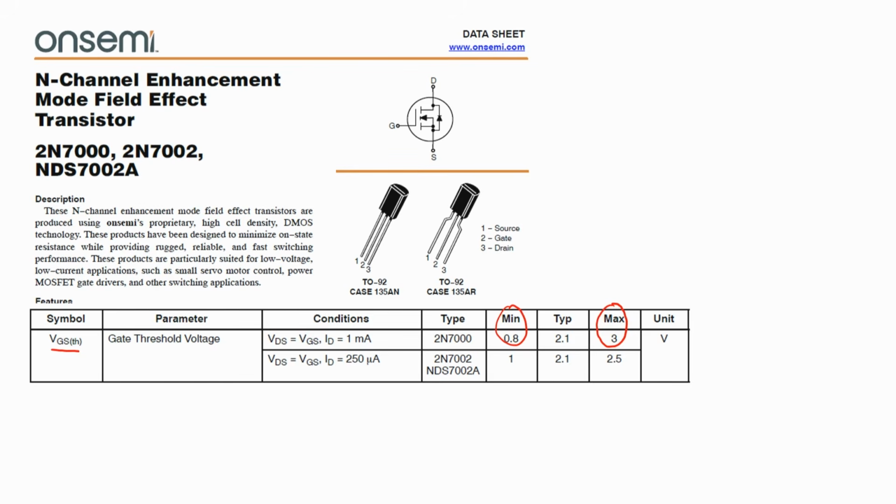With a bipolar transistor, you know that around 0.7 volts, that transistor is going to turn on. With a MOSFET, even if you choose the same MOSFET, well, it might turn on at 0.8 volts, it might turn on at 2.1 volts, it might turn on at 3 volts. We don't know. It might be random. So whatever circuit we design, we're going to have to accommodate different threshold voltages. If the threshold voltage changes, it effectively means that this entire curve shifts from left to the right. Our circuit has to be able to deal with it.